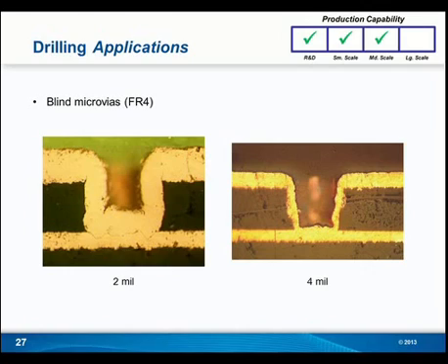The great thing about UV lasers is that, as we've been saying this whole time, you're able to control the power of your laser so well that it doesn't matter how deep or how much of the substrate you have to drill through. You're always able to stop and set your parameters such that sometimes you may have to stop after 100 microns. In a different application you may have to stop after 250 microns, and you're always able to do so because you're able to control your laser power so well. This application can definitely be used in R&D and small and medium and large scale production. And because you're working with a 15 to 20 micron beam, you have a lot of options in terms of your hole diameter as well.